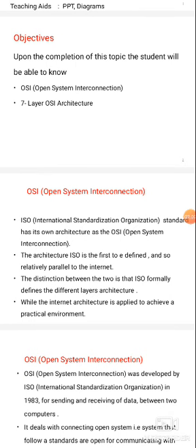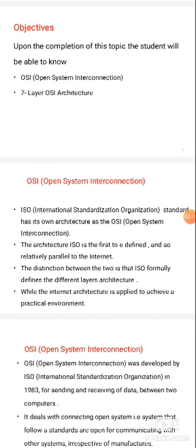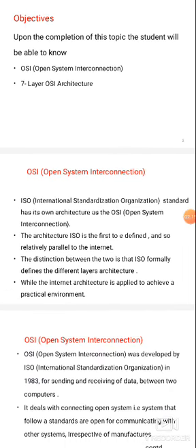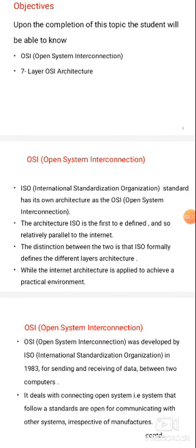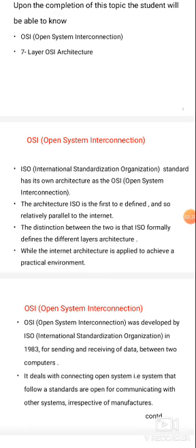And also analog communication and digital communication. Analog is nothing but the amplitude of the signal continuously changing with respect to time. Digital is nothing but a discrete signal. It contains only two levels, binary 1 and binary 0. Binary 1 indicates high position, binary 0 indicates low position. The best example of analog communication is the sine wave. A digital example is the square wave.